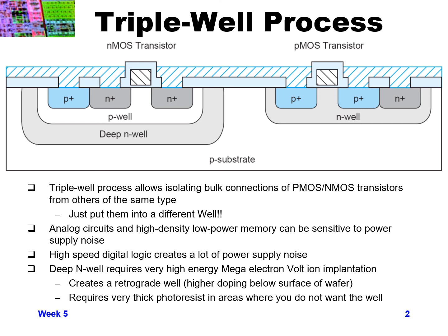Here we're starting with a P substrate, like our typical process has been, and we have an N well off to the right, which is our standard N well, and we can put PMOS devices inside of that N well. And so we have P plus diffusion regions, and then an N plus diffusion region, which is a voltage contact to the N well.